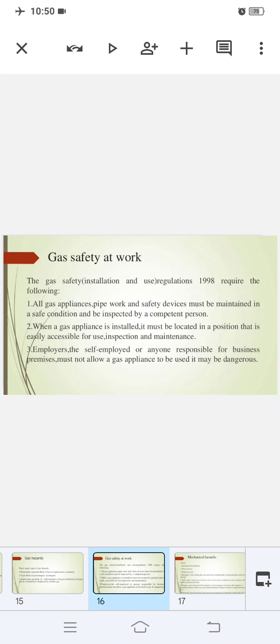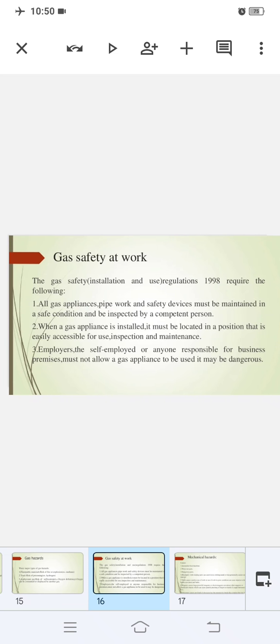Dust particles are thrown outwards to the wall of the separator and they slide down towards the hopper, from which they can be subsequently withdrawn. The cyclone separator is suitable for attaching to the machine, and can form an integral part of the design of certain mills and mixers in which dust is produced.